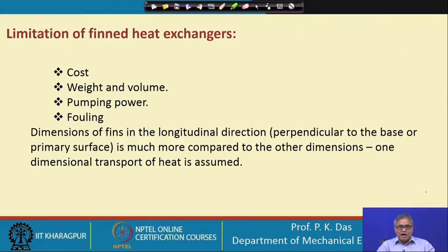For a racing car, an automobile that we want to move with a high velocity, we want a very efficient heat exchanger by putting a number of fins, but we have to be careful, because in all these cases the addition of fins not only increases the volume, but also increases the weight of the moving system, which means more traction power. So, we have to be careful.